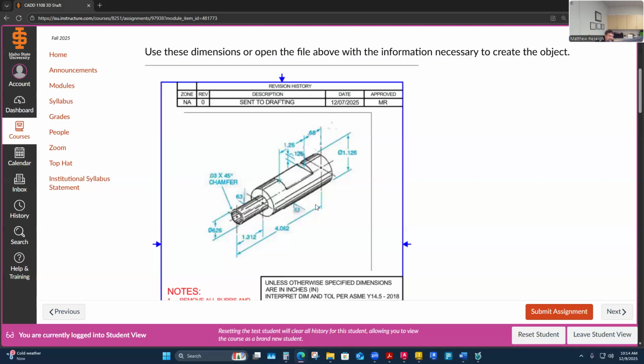so I think I'll add the chamfer, which is this little 0.03 chamfer to the end. It's just kind of a little detune, like the machinist would detune that, so it's not a really sharp corner on that edge. It can allow it to slip into a bearing easier. I call it detuning the end there, just knocking that sharp edge off the corner. This one here has a sharp edge corner, and so would this back one, which isn't totally normal, I guess.